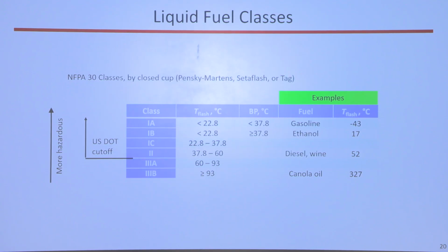And that's why in my laboratory at 25 degrees C, even with the blowtorch, I wasn't able to ignite a pool of diesel. So not only is it an interesting test, I like it because you can do hand calculations and learn about the thermodynamics of this, but it does have a true application for transportation safety.